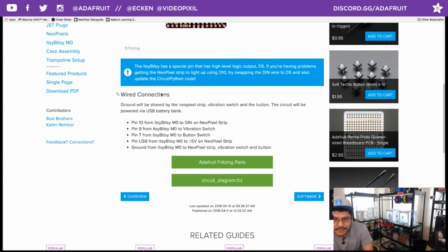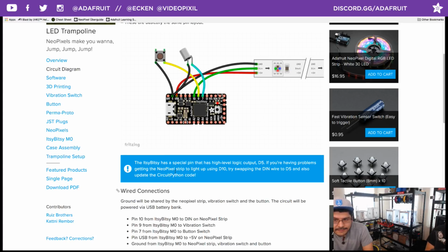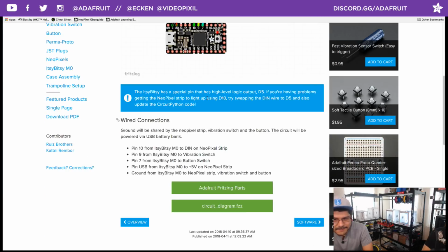That's pretty simple. Oh, we got a special note here from Lamar that if you find that the pixels aren't working the right way, you can just try using that special 5-volt data pin that we have. It's called pin 5. It's right over here. And that way you'll get 5-volt logic coming out, because NeoPixels normally like 5-volt logic. Some of the older strips do, but the newer strips that we're using, they don't care. They're like, yeah, sure, 3's fine. And they seem to work fine.